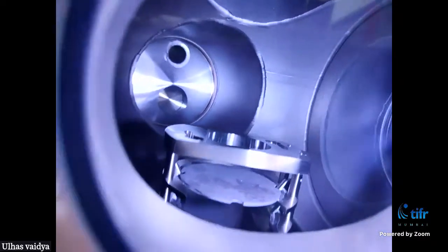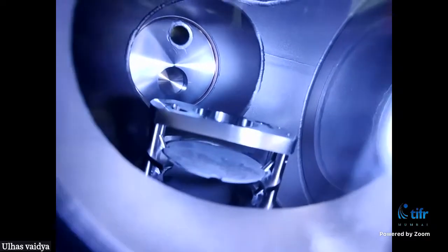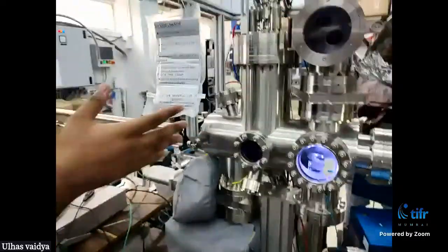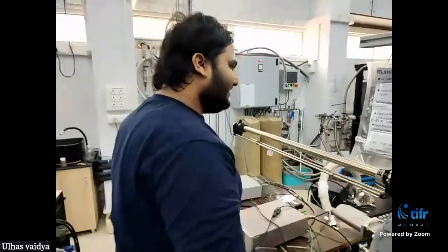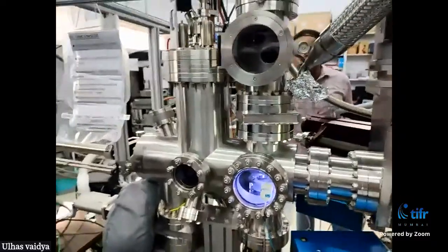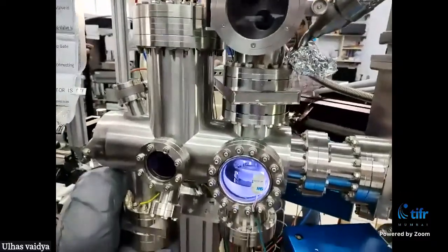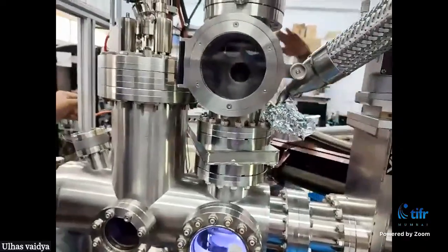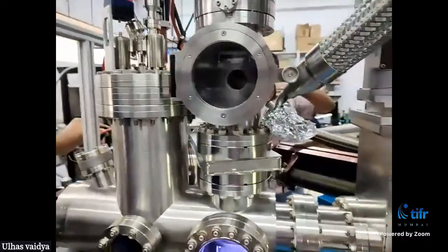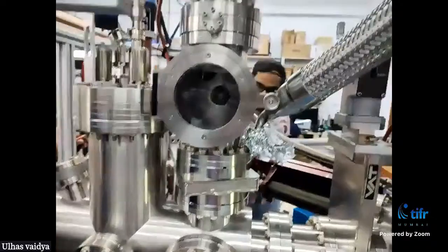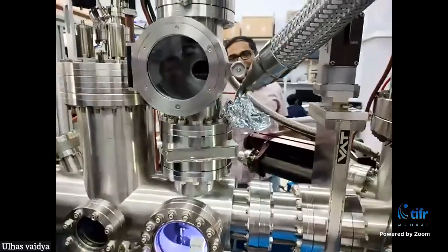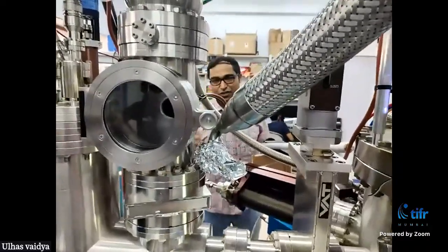Yeah, we definitely need to close the gate valve because the whole process is like having a load lock system, so that when we increase the pressure here, it doesn't increase there. So I am closing the load lock now, separating the load lock from the buffer chamber by the gate valve, so that the pressure here, which is not as good as in the buffer chamber, does not affect it for too long. We want to minimize the time when the load lock is open to the buffer chamber. It just took us maybe a minute, and that is only the time which sees the bad pressure.